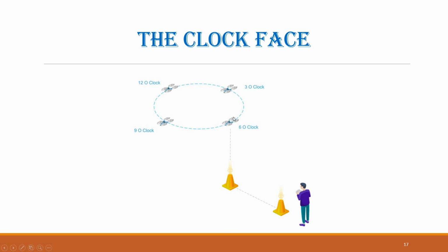Once oriented, gently push the drone forward while applying slight rudder input to guide it toward either the 3 o'clock or 9 o'clock position. As the movement begins, turn the drone so that it faces away from you. This ensures that when the drone reaches the 12 o'clock position, it will be approximately 15 meters ahead.